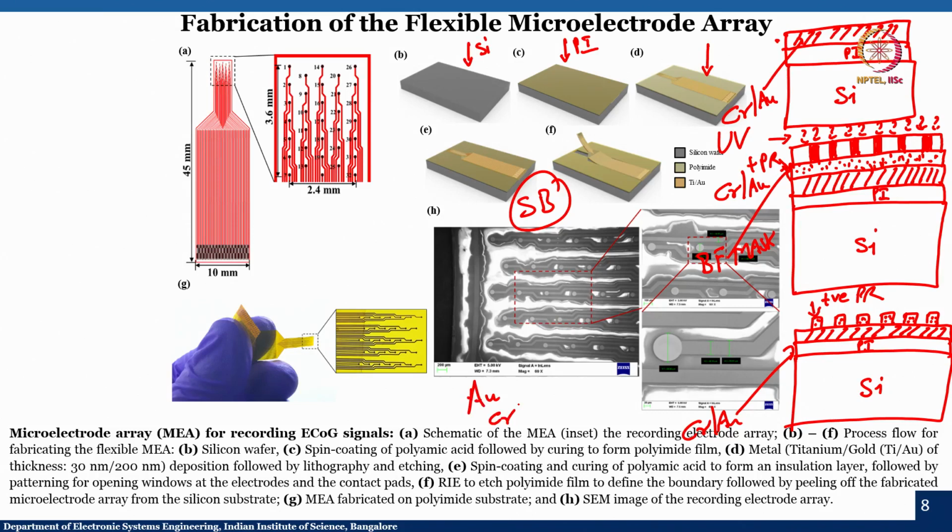Whenever you dip any wafer with photoresist, or perform any chemical reaction, you have to wash it with DI water. Once you dip the wafer in the gold etchant, you take it out and rinse it with DI water.